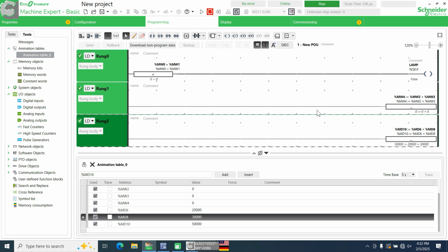The regulator is like a valve. Open how many percent? Because if a valve just opens and closes, it becomes digital. If the valve is at a value, then that becomes analog. So controlling the valve to open is the output. That means analog output, 4 to 20 milliamps. Yes, correct. This one will go to your device, that is your temperature regulator.